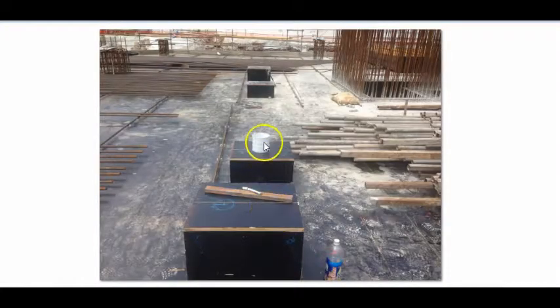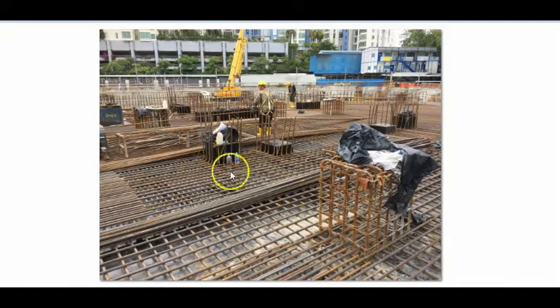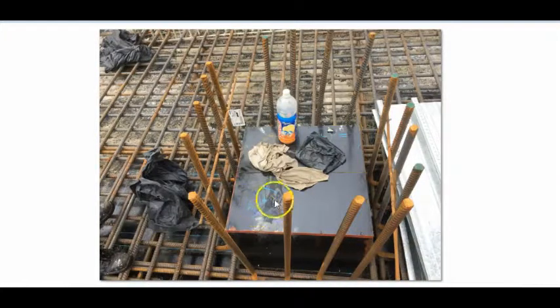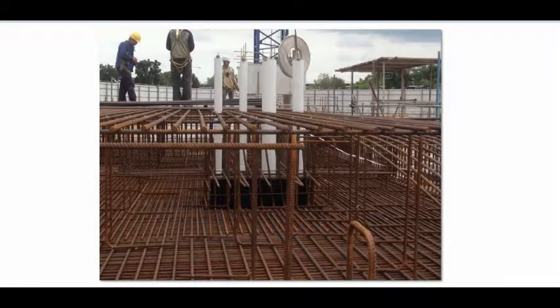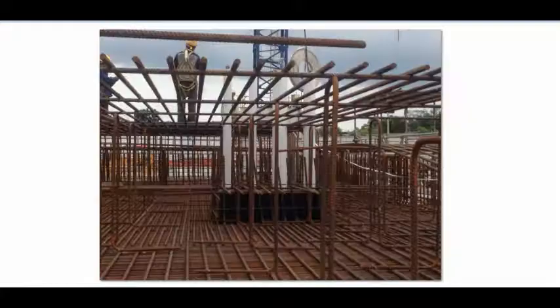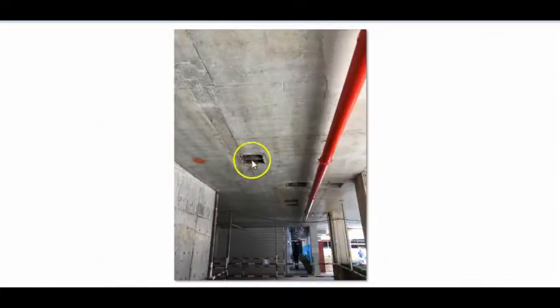With all this formwork for the recess, the rebar will be installed accordingly by the builder. And we will mark our piping on the recess as well and start to install the piping. And this is how it looks when the casting is completed. The opening access is ready for installation of the sanitary piping, or the opening for the sanitary.